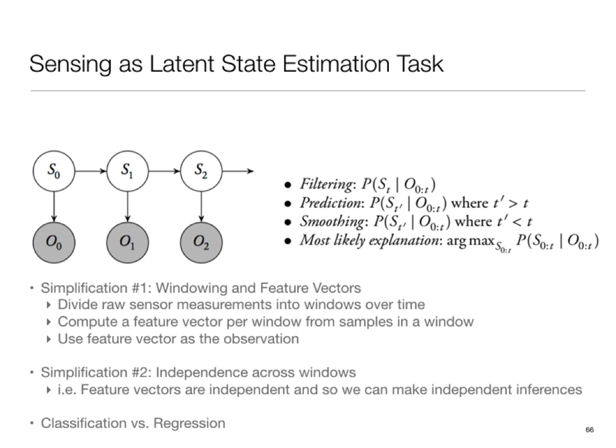So one very common simplification is that we are going to window the sensor data. So basically you're getting some sort of sensor waveforms as observations. So you window them. You would think of them in some windows of time, the intuition being that the world operates with some time constants. So faster than that makes no sense. So you could assume that things were kind of stationary during that window. So you divide the raw measurements into these windows.